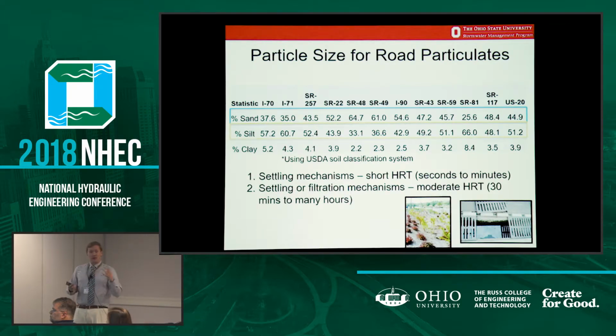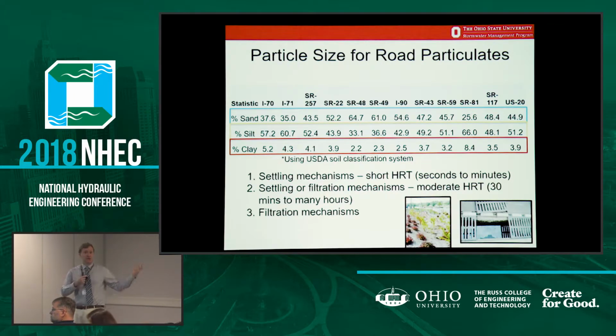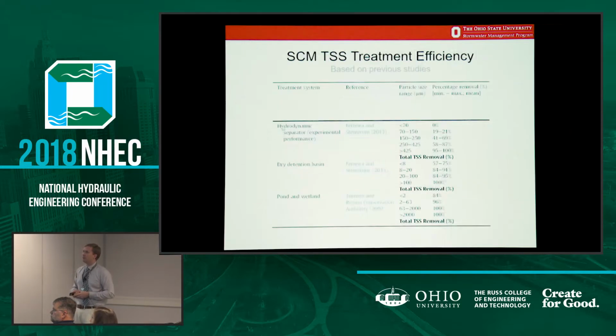The silts, right, you're now getting into a moderate hydraulic retention time, where you might need 30 minutes to many hours' worth of retention time within a BMP in order to take care of those. And then clays, you're really getting to filtration mechanisms, right? We're getting away entirely from the swales and filter strips and the easy BMPs to install in the linear right-of-way.